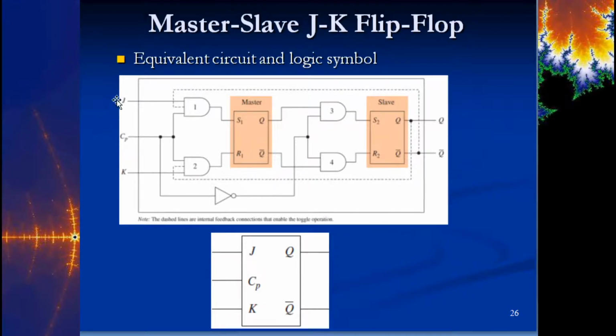So initially, this kind of looks like we don't have the same cross-couple design, but that cross-couple design is both in the master and the slave here, okay? Those are just SR flip-flops. Can you see that? Right, S1, R1, that's an SR flip-flop. This is an SR flip-flop too. Okay, so we've got this gate circuitry in front here, so let's walk through this and see what happens.